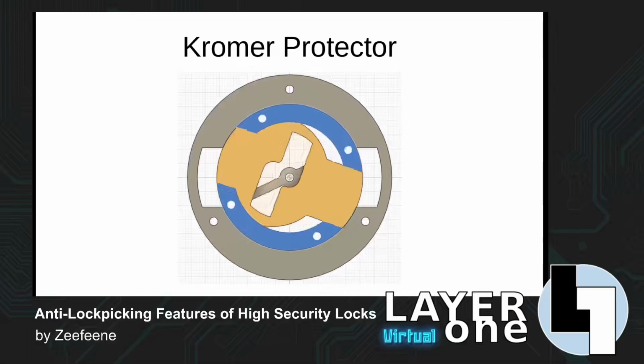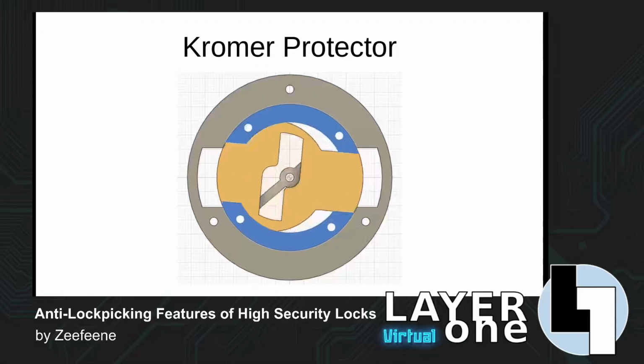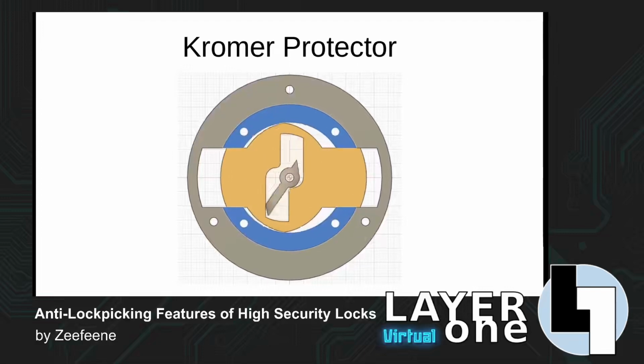In a lateral motion first, until the other side of the key makes contact with the other side of the wafer. So that's what we see when the lock starts to turn, because at that point the wafer can no longer move side to side, it is jammed in place by the key, and so that rotational force in the key is then transferred to the wafer, and that is then transferred to the core, which is that blue portion that you're seeing